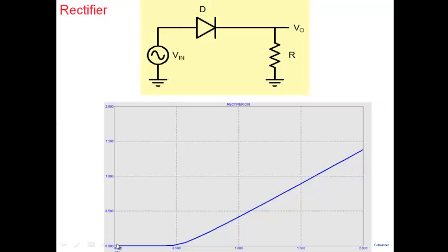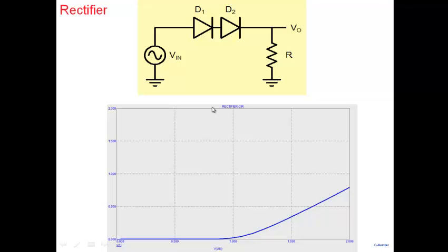So in this case, we see here that the threshold is close to the cut-in voltage of the diode here. If we want a larger cut-in voltage here, well, one option is we can put two diodes in series here. And in this case now, instead of earlier starting from, let's say, 0.5 or 0.6 volt here, now it will start from about maybe 1.2 or so here. So by putting diodes in series, one could get threshold voltages which are multiples of the diode cut-in voltage.